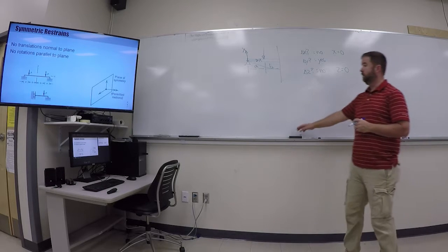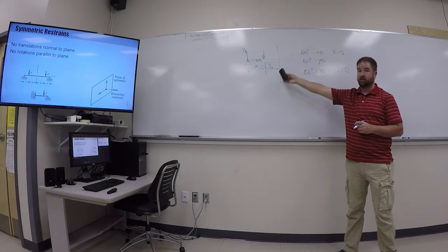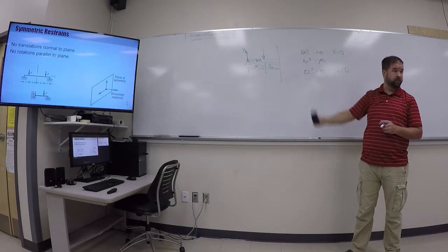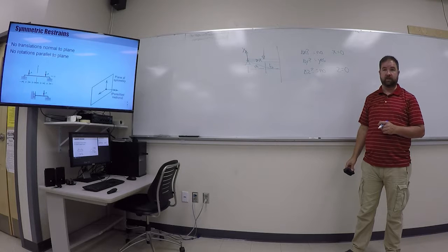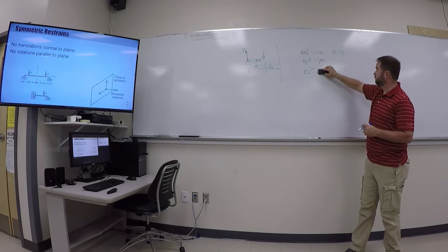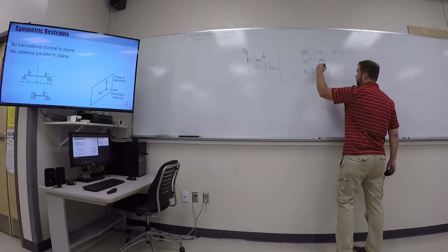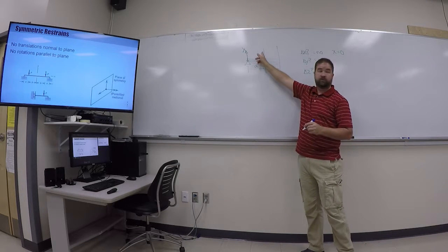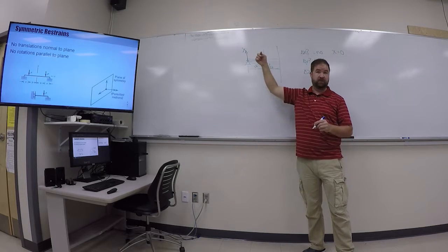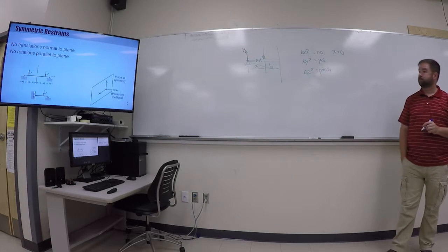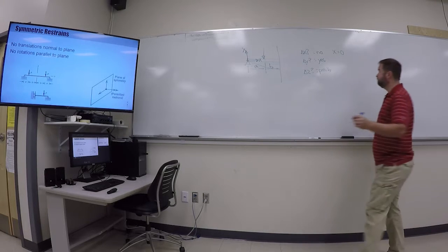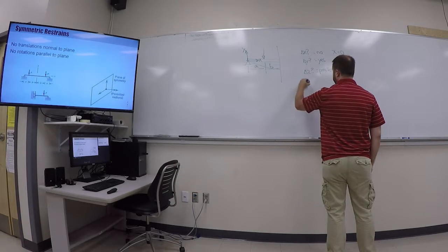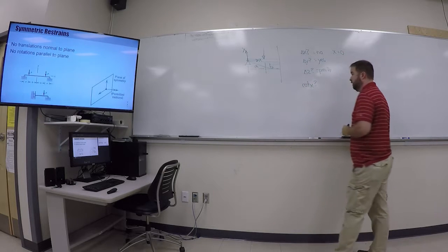Actually, I'm going to change that a little bit. Because of the loading that we have here, the z doesn't change. But could we put a load on in the z direction and it still be symmetric? We actually could. So I'm going to erase that. Does z change? And I'm going to put possibly. It doesn't because of the direction that I have the load set here. But we could put a force in the z direction, it could still be symmetric. Okay? So is there rotation in the x direction?